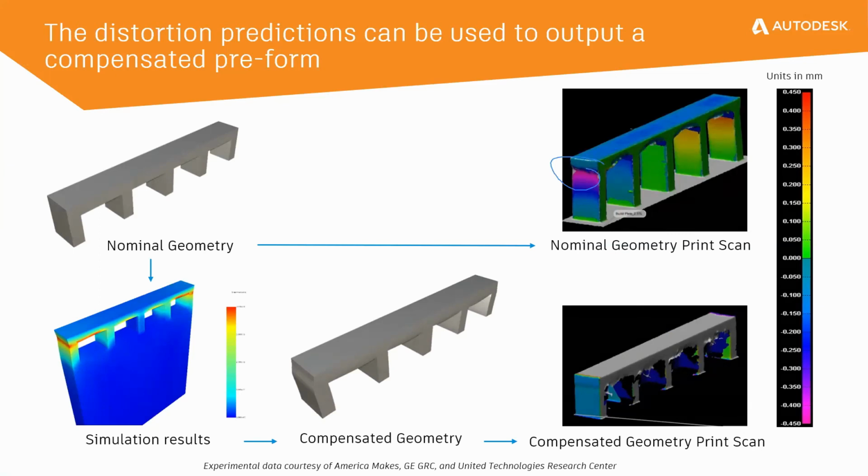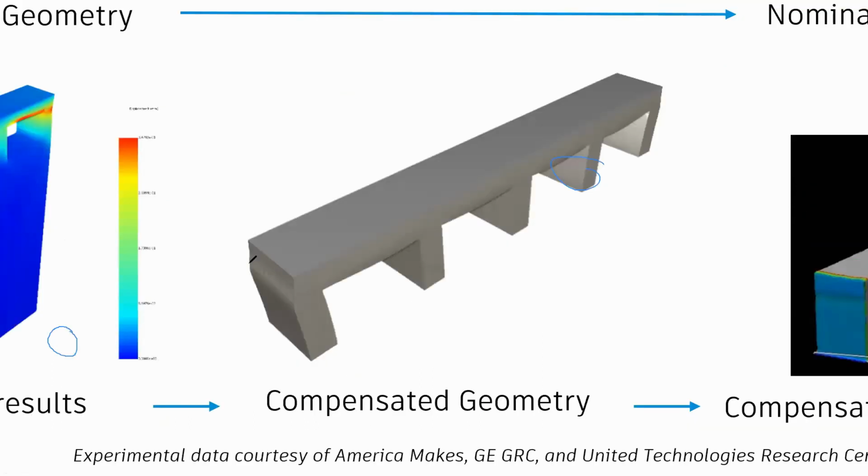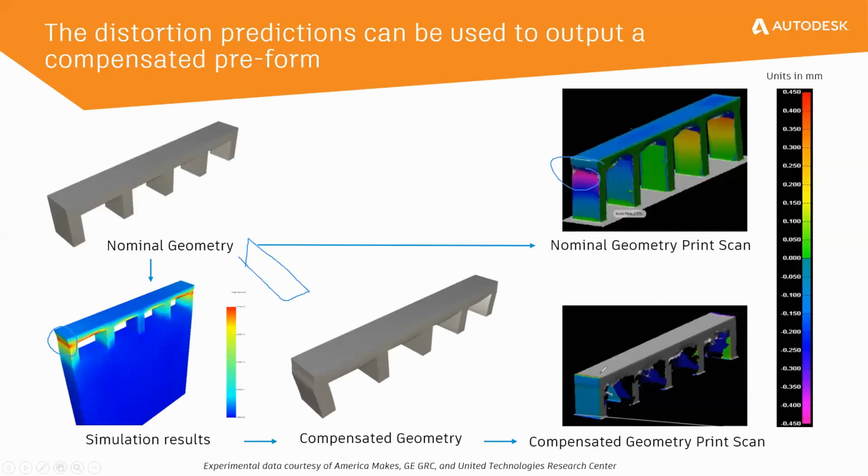Now, if you were to simulate the part, we also show the same failure, but if you make a warped geometry, you will end up with having something which is essentially moved in or pre-compensated or pre-warped in the opposite direction. So we basically squeeze it the other way so that when you print it, you actually get it to more or less in line with what you wanted to see. So you now see that over here, this thing is going to be straighter as compared to what you did if you actually printed the actual part that you wanted to print.